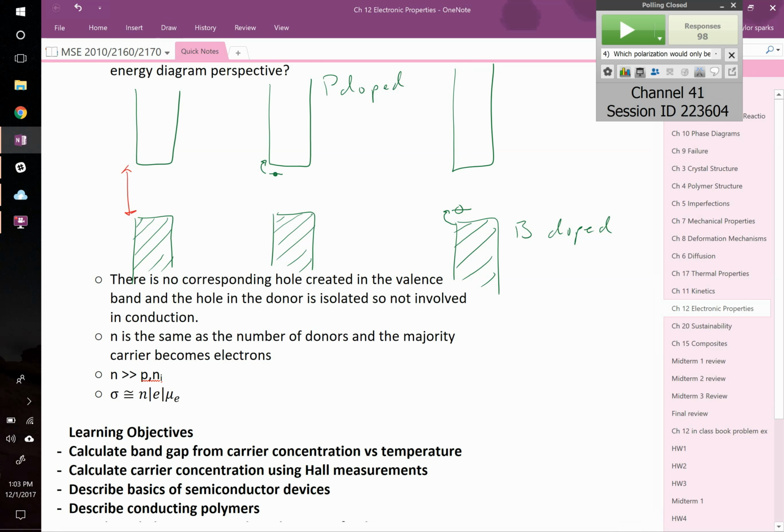So because of that, you don't see big bands from the dopants themselves. You just see little impurity bands, right? You're able to put like one little impurity there or one little impurity there. So it's not a full band itself, but it is a spot, right? It's a spot where you could then take this electron, go up there and occupy that spot, okay?